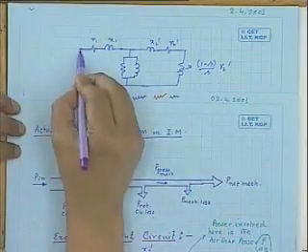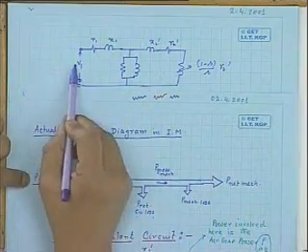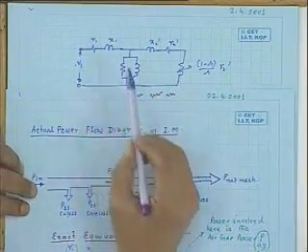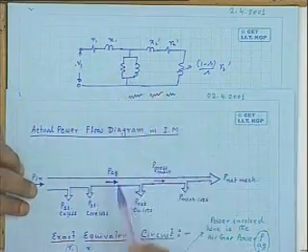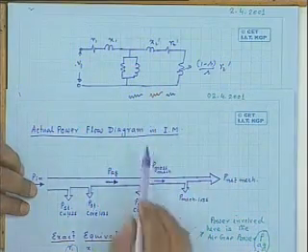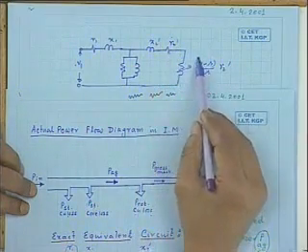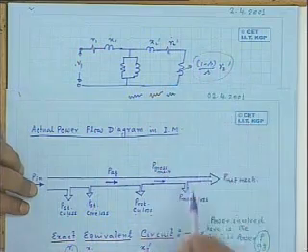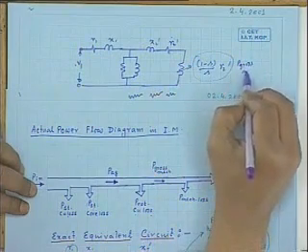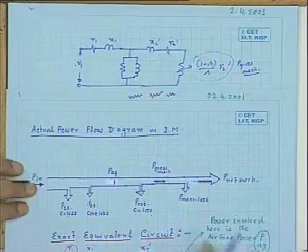And this is your supply voltage V1. So the one-to-one correspondence will be: this is the input power here at this point. Then stator copper loss is taking place here. Then core loss is taking place here. Then rotor copper loss, R2 dashed, is taking place here, and this one is therefore the gross mechanical power, P gross mechanical, out of which a portion will be lost as mechanical power loss in the machine.